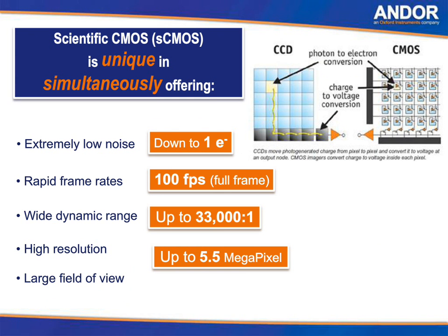So if I look at the CCD, the charge enters into the pixel and then is effectively clocked down and then out along the surface. So it takes that individual photon a long time to move through the clock down and along. And that is the effective frame rate. So most CCDs are working in the regime of 4 or 5 frames per second.